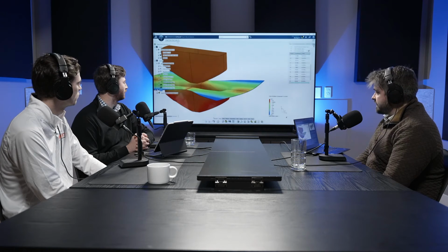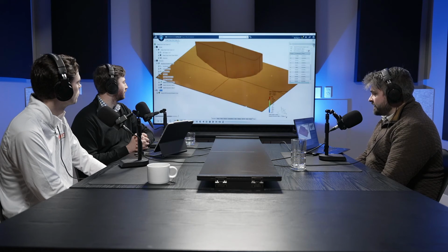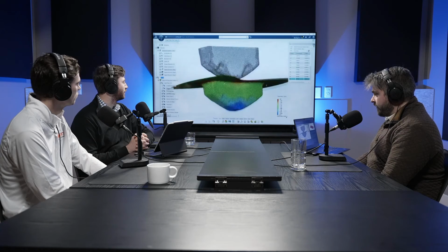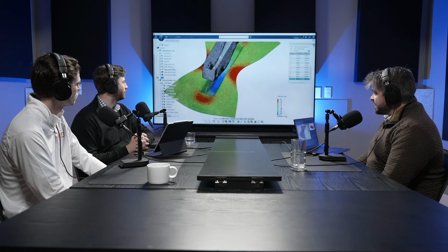And then we can look at our results. The results that you would see here are not that much different from what you'd expect from any other simulation tool. If I'm looking at this from a structural component, I'm looking at things like von Mises stresses, factors of safety, things like that. Where it differs is that I do have access to some higher end things. Like I can run a destructive kind of simulation, and I can see those sorts of simulations happening as I'm running through this. I can also activate and deactivate plots if I want to understand a better way my part's going to look here. But this is the interface. This is sort of how it looks.